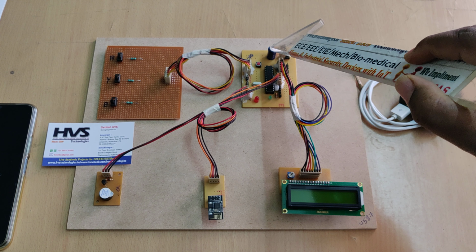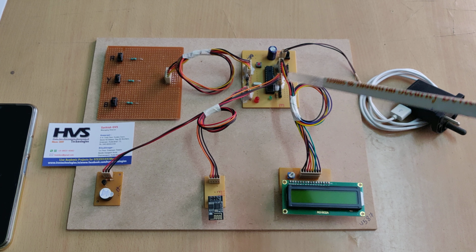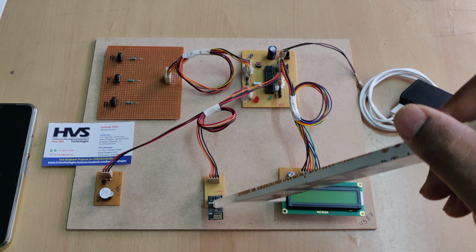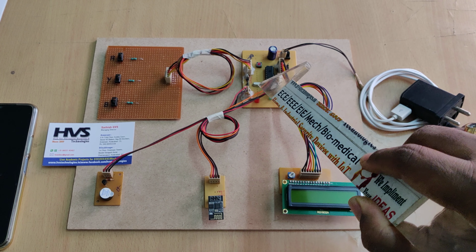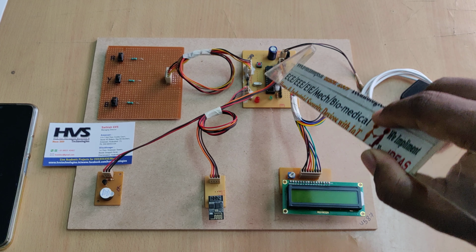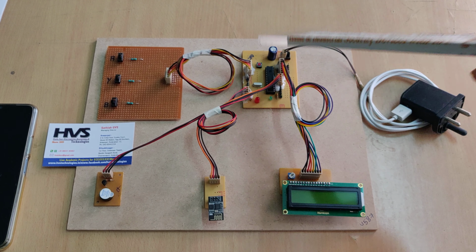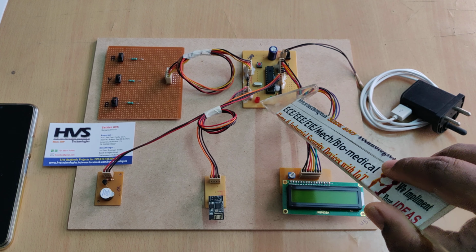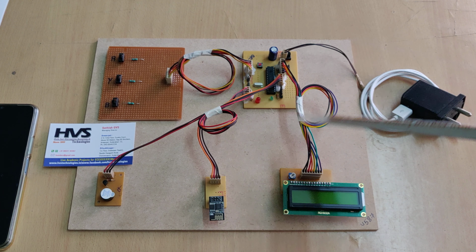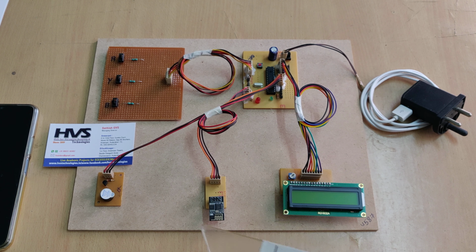Here one more capacitor is there in order to maintain the maximum current while executing the steps, means while sending the data to the Wi-Fi module. And we are making use of one crystal oscillator, a 20 megahertz crystal oscillator, the steel coated one. This one is a reset switch in order to restart the microcontroller. The red color is the power LED indication, and the green color is the program LED indication. It will blink for every loop of continuous execution.